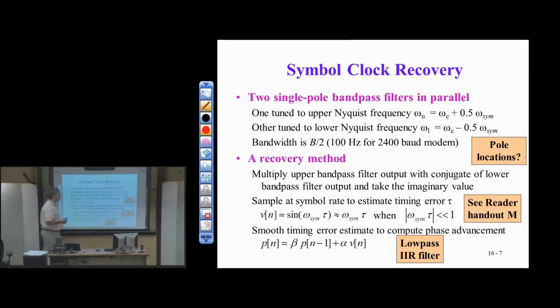So if you remember, what's the fastest continuous time 2-PAM signal that we can have? It's going to be alternating: symbol amplitudes alternating plus D, minus D. So consider the most extreme case, plus D, minus D, plus D, minus D, etc. That's the fastest alternation that we could have in 2-PAM.